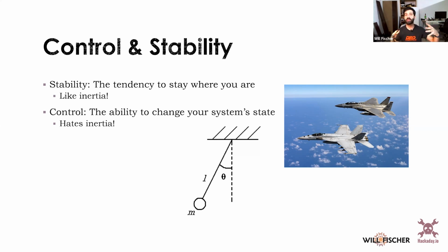So like in big cargo aircraft, they put the fuselage below the wings, and then the weight, the force of weight, keeps that plane very steady as it's flying. You don't want that for a fighter because you want to be able to move very quickly. Those cargo planes don't roll over very quickly, and they certainly don't bank very quickly. So with a fighter, you put everything pretty close to the center of mass so that you can rotate and pitch really quickly. The result of that is that you have very good control, but very low stability.